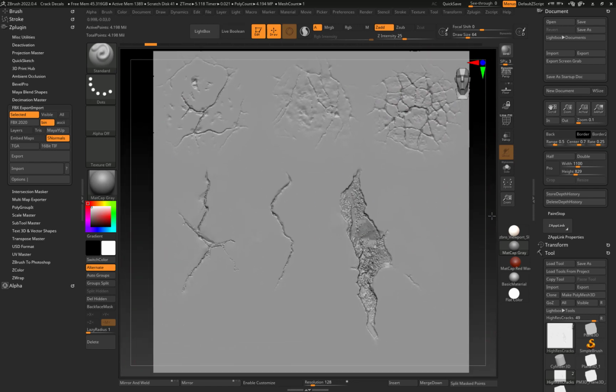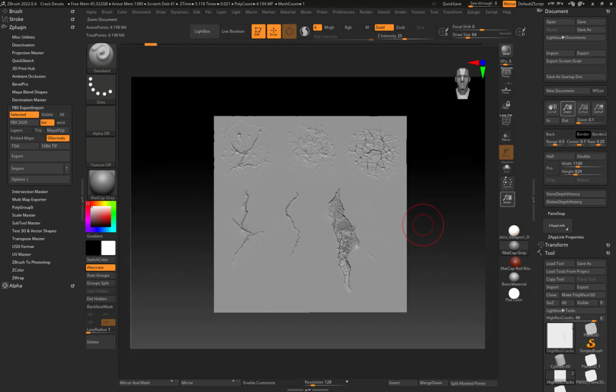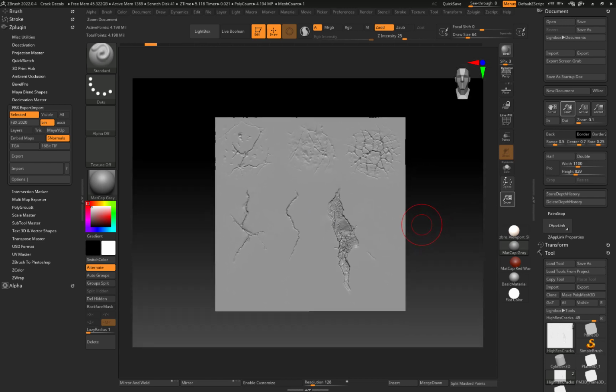That's actually not the size of the canvas. That's the size of the sculpting area you're working in. So what you need to do is zoom back out, and that's what this does. It zooms out to the canvas size, and you can keep going, and as soon as you stop seeing those lines, you know that you see the full canvas. And since we want to export this out as a texture at 2048, what we want to do is just come in here and go 2048, and go to here and say 2048, like that, and then resize.